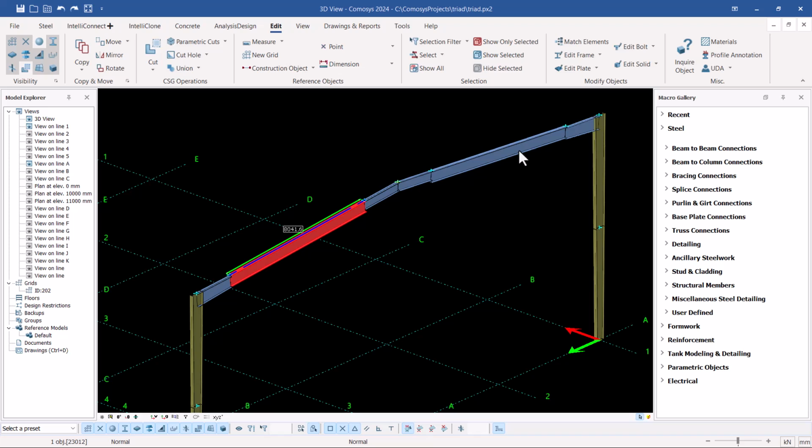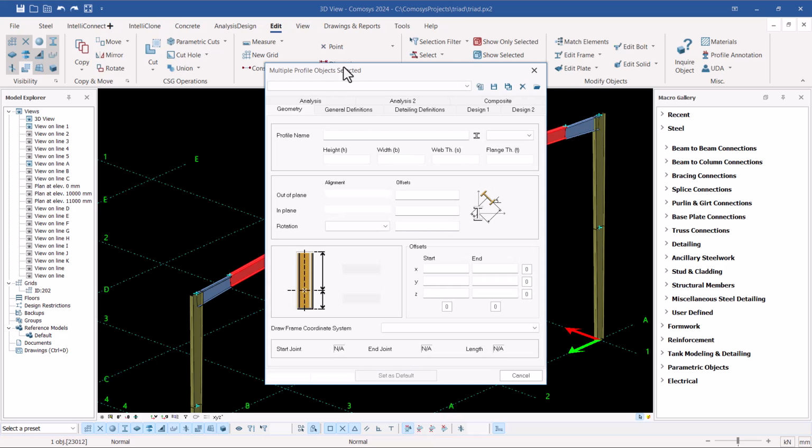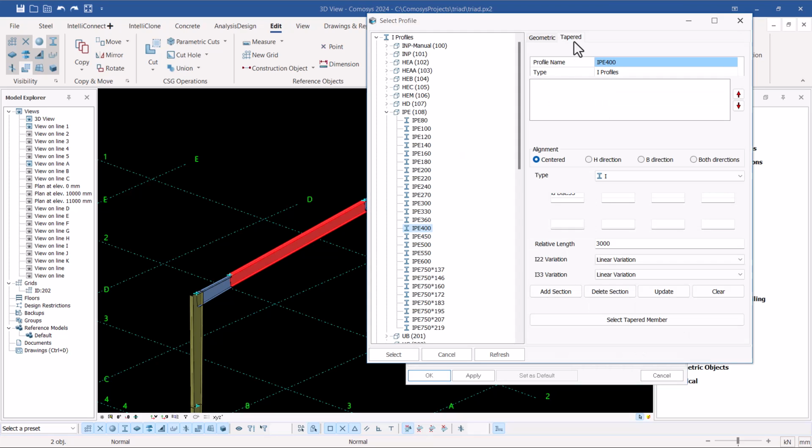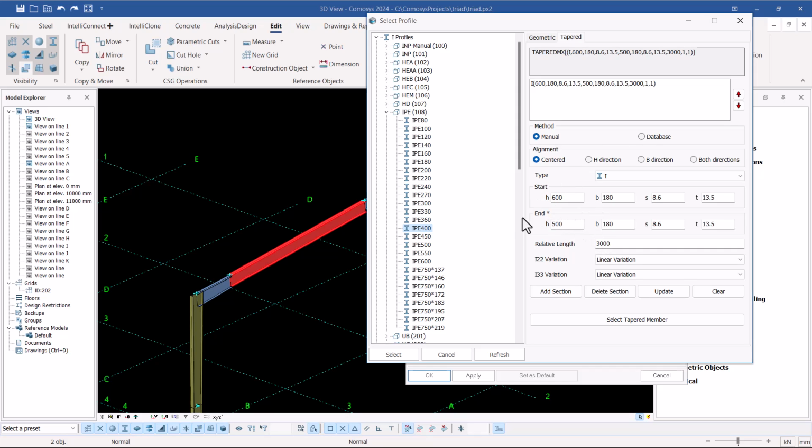So I want just to make it as a tapered member, but all of them will be the same. There will be no taper, but I'll just edit it or customize it as a tapered member. So let me just give some time to bring it up. So if I come to this and come to taper, in here I'm going to change everything to 5 because this far end is 5. So let me first of all clear the current details here and change this to 5 millimeter.